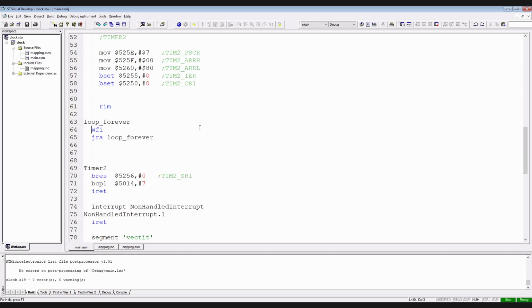It's better to add this instruction in real-world programming of our discovery board, but sometimes in the case of debugging, we have to comment such instructions referring to the interrupt, because they may cause problems during the debugging process.